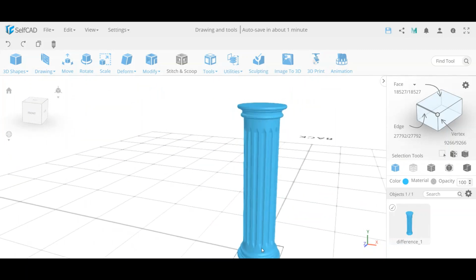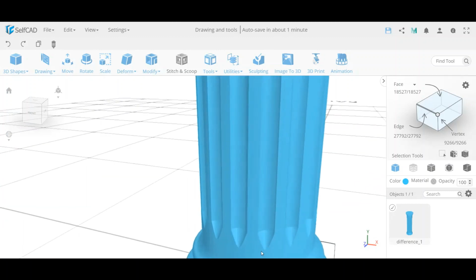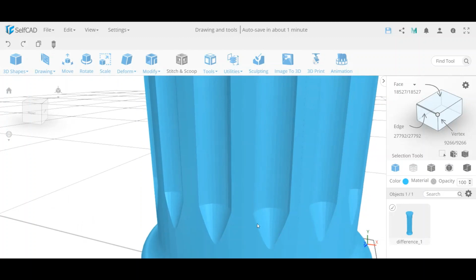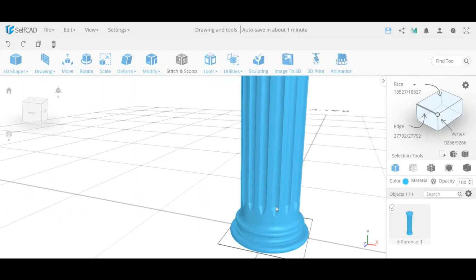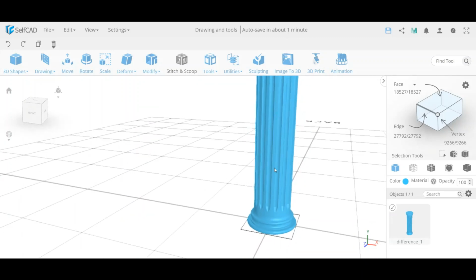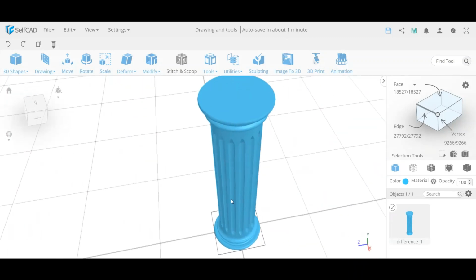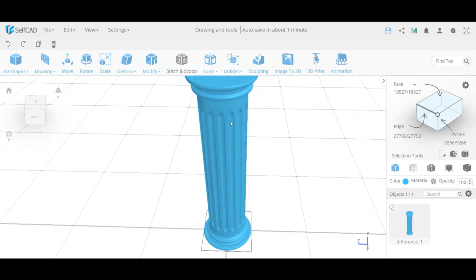But you can obviously, if you see what I just did, you can use any other shape to reconstruct them. And to be honest, I think the edges over here look even nicer. It looks really clean cut compared to the original one. Maybe it's still a little bit too pointy, but you see, you can play around. You can take a cubic shape, you can take any other shape. There's another option that I tested before, where I can loop select every second face, and then use extrusion with inset kind of combination, macros. But in this particular case, this was the simplest way.